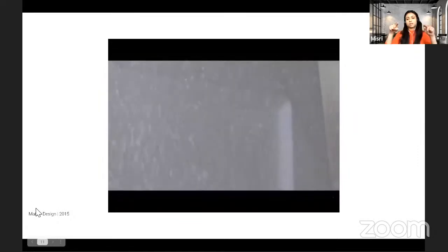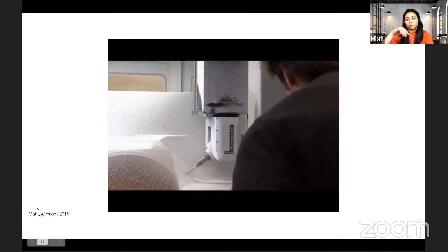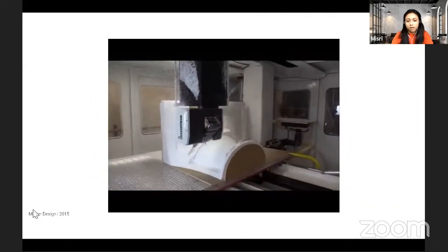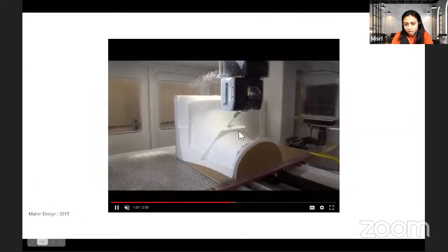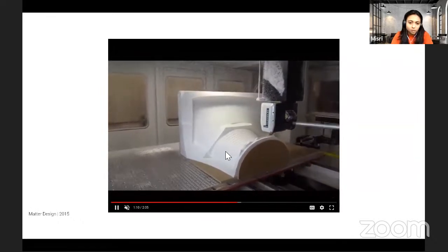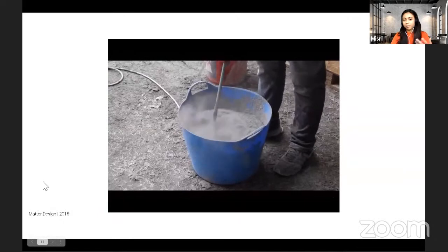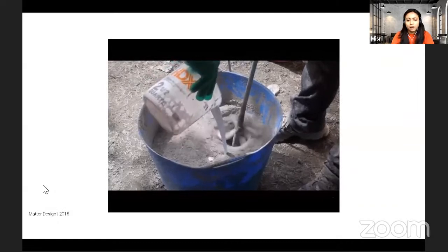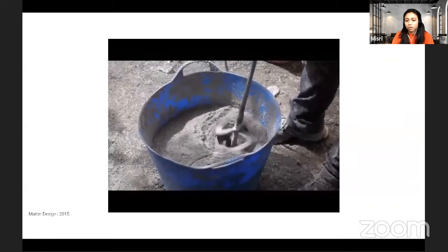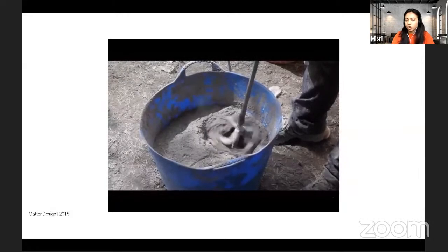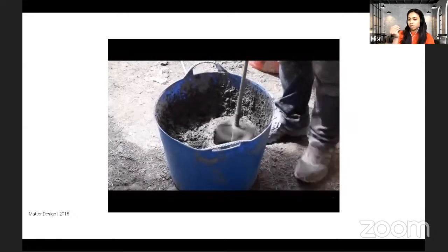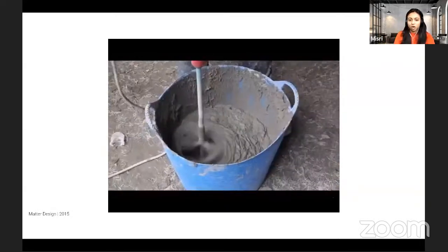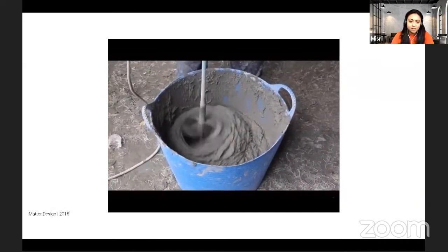As you incrementally move along the surface, that's how you're taking all the material out. And what's left behind, like you see these simple striations on the first half, are called the roughing passes. It's not the final product, but the first pass is done to take out all the key material that you know you're not going to need for sure. And then you go back with a much smaller drill bit, maybe 1/8 of an inch, to really detail out your entire geometry so that it creates a seamless form.